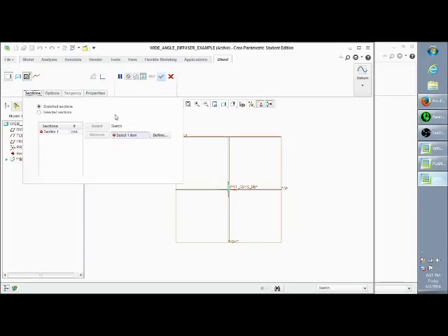In this first section, we're going to create that first box shape that makes the smaller face of the wide angle diffuser. For those of you who haven't taken measurements yet, the wide angle diffuser is part of the wind tunnel design where the blower for your wind tunnel is hooked up so that it pushes the air rather than sucks it through, and the wide angle diffuser is the side that hooks up to the blower.